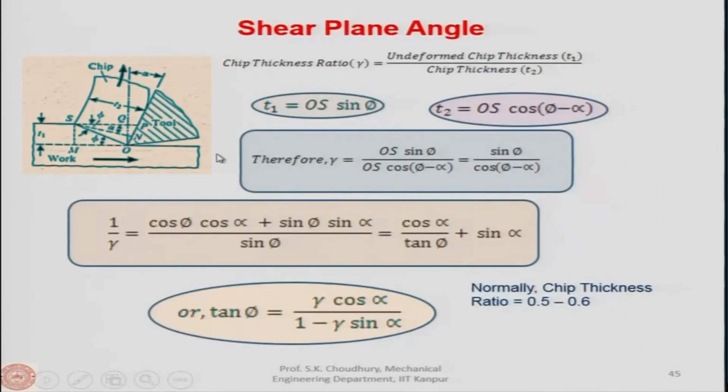The second inaccuracy may creep in when these points are to be connected with the tool tip, because otherwise you will not get the accurate value of this angle. Because of that, the measurement is not followed popularly in practice, and the value of the shear plane angle is taken analytically. So, let us see how this shear plane angle can be analytically found out.